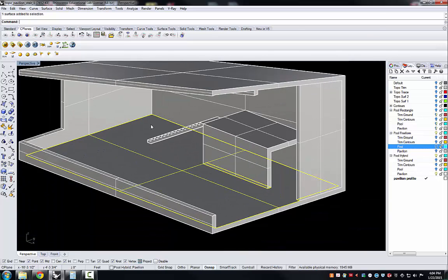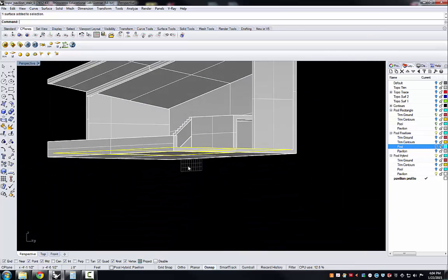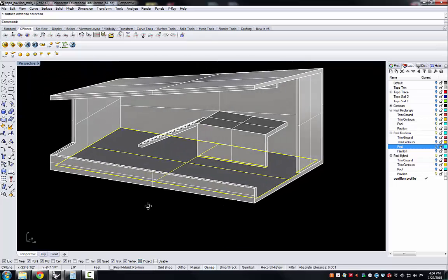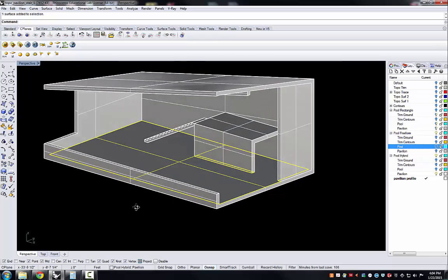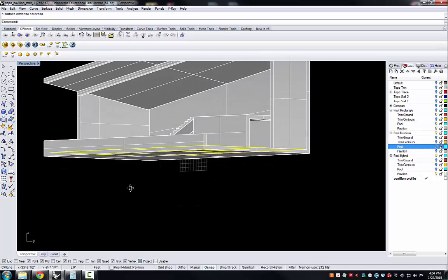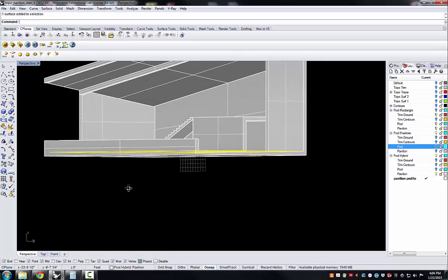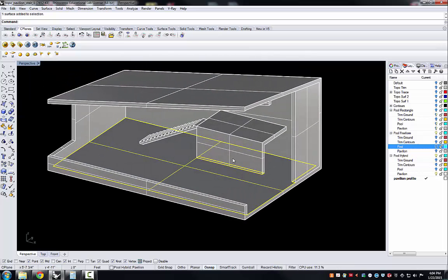And we've learned about moving the construction plane, as we did, you can still see it here below, to a surface that we wanted to use as a reference surface. If we want to keep that construction plane and save it for later, it's easy enough to make a new one, but we can also always save a construction plane for future use. So I can click on Save C-Plane by name, and give it a name. It suggests C-Plane 1. I can call it stair, and I can retrieve a named construction plane to be used later.